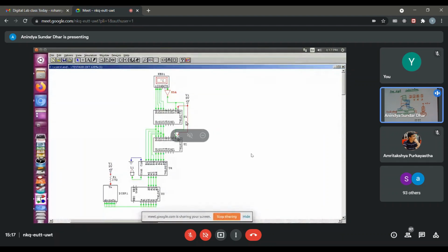But it's 50% utilization, so it is gross underutilization. I could have used just a single one. In practice, in the lab, you are supposed to use the single one. Right now, I am not using the higher order 4 bits in any of these 273s. However, if for some reason I would like to use the higher order bits of the ASCII keypad, then I need not change the arrangement. So you can still keep it.